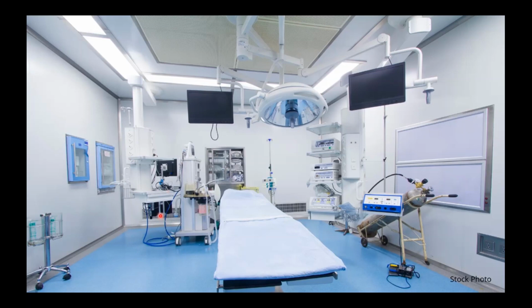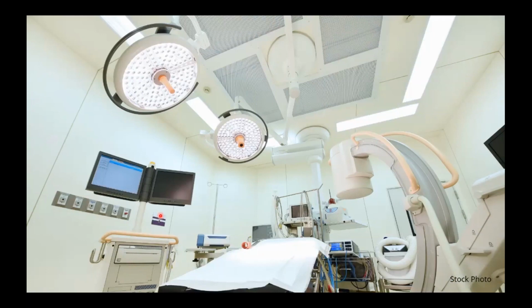So here we see another good example, and this is also ASHRAE 170 compliant. We can see our laminar flow diffusers are located in the primary diffuser array directly above the operating room table. They've mounted a boom right in the middle. So you can kind of see why ASHRAE dictates 70% coverage for laminars and then leaves 30% for everything else, because you have penetrations of surgical booms that make it impossible to mount a laminar diffuser there. And here we see a return grill on the wall. It's kind of obstructed by the OR table, but generally this is a good layout.